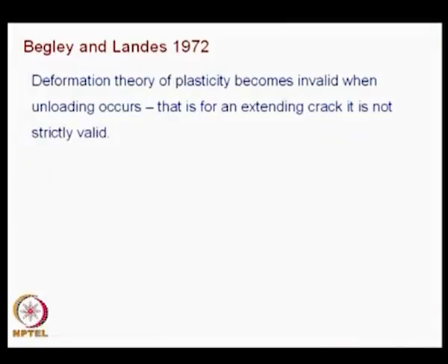So, that is why he says you take two specimens which are of different crack lengths. In fact, Begley and Landis did that kind of experiment, and that is what is summarized here. Deformation theory of plasticity becomes invalid when unloading occurs. That is, for an extending crack, it is not strictly valid.